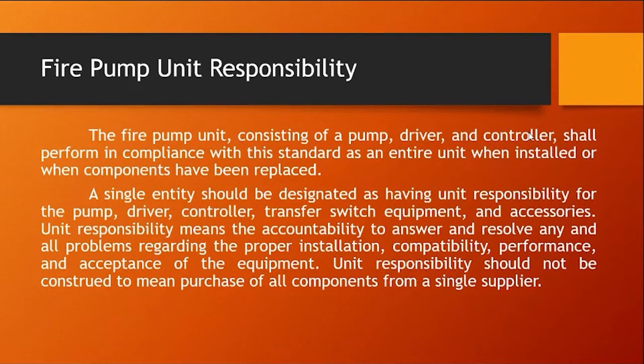Fire pump unit responsibility. The fire pump unit, consisting of a pump, driver, and controller, shall perform in compliance with this standard as an entire unit when installed or when components have been replaced. A single entity should be designated as having unit responsibility for the fire pump, driver, controller, transfer switch, equipment, and accessories. Unit responsibility means the accountability to answer and resolve all the problems regarding the proper installation, compatibility, performance, and maintenance of the equipment. Unit responsibility should not be construed to mean purchase of all components from a single supplier.